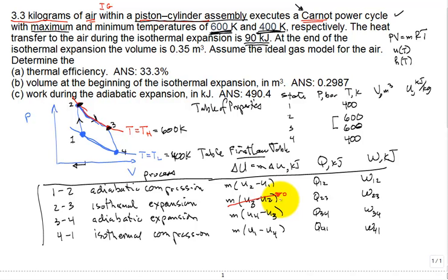And then we look and we say, well, what about the process from 4 to 1? Wasn't that isothermal? Yeah, it is. And so this also is 0. Let's say it's 1, 2, 3, 4. I have 12 values in this table that I'm trying to fill out, and I just figured out 2 of them are 0. Okay, those were the changes in internal energy.